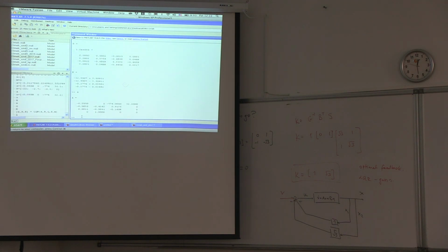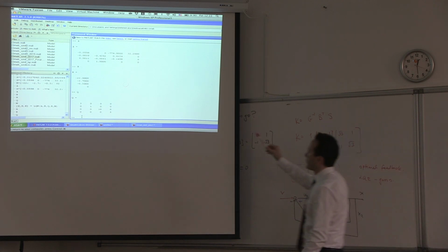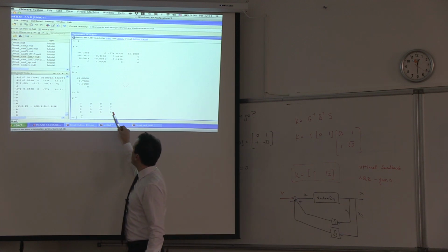So this was the lateral dynamics that we use for an airplane. Okay, and this is what you did in your homework, and that it's a 4x4, right? And that was the B matrix that we use for this one control. Since we have 4 states, I'm going to use an F matrix that's again a 4x4. This is the F matrix that I have used in the past. The diagonal is 3, 1, 10, and 5, and I have zeros everywhere else.